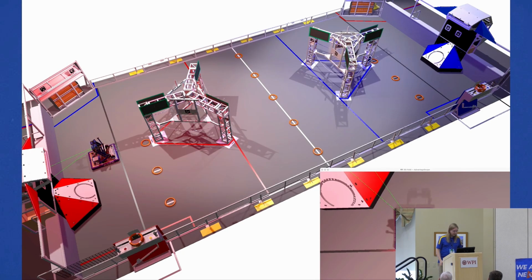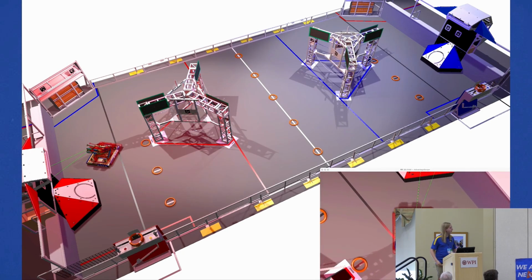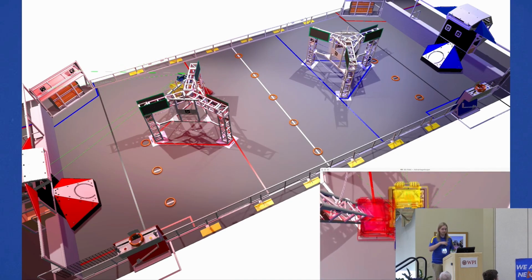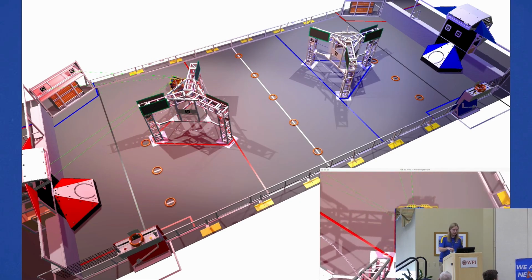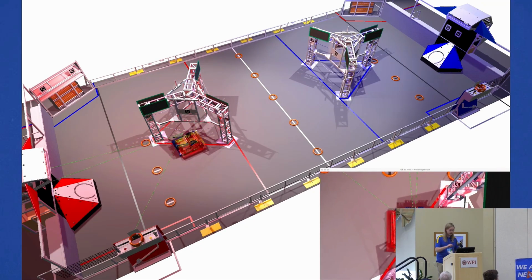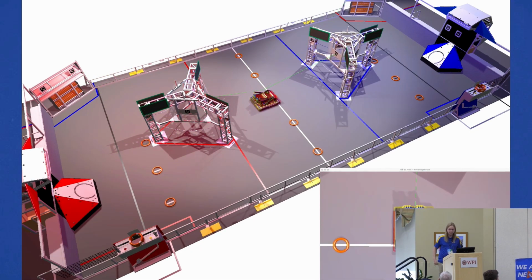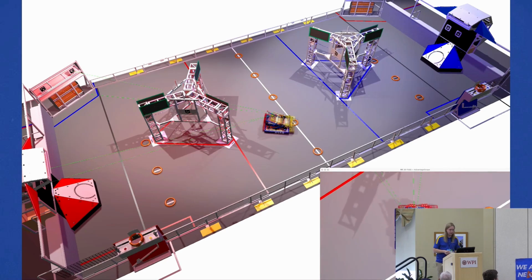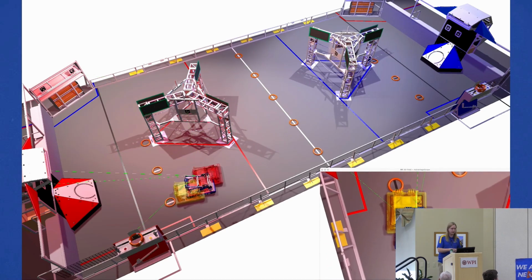Okay, now finally, here's just a fun example to show the importance of why we do all of that filtering and focus on having a wide field of view with multiple cameras. This is from our first 2024 event. In the center, the real solid robot is with all 4 of our cameras and all of our normal filters running. The yellow robot shows if we only had 1 camera, but with all of our standard filters.